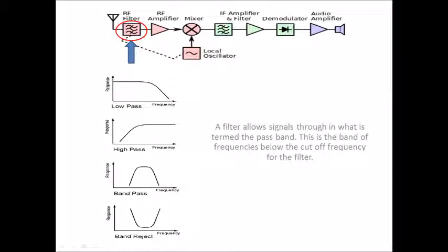Now moving on to the radio components, let's study about the antenna first. In an FM radio receiver, it is the antenna which intercepts radio waves and converts them to tiny alternating currents which are applied to the receiver. The receiver then further extracts the desired information. Radio waves are electromagnetic waves generated by a radiating element called transmitting antenna and absorbed by receiving antenna. RF filter filters out the required frequencies from the frequencies received by the antenna.